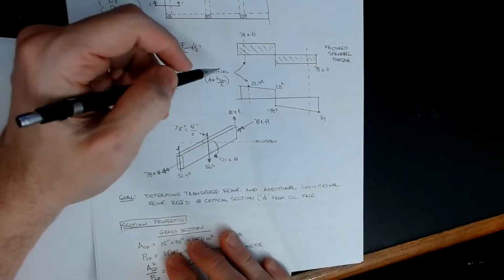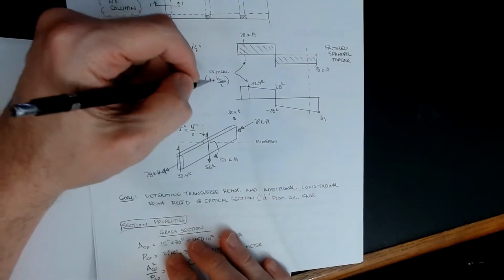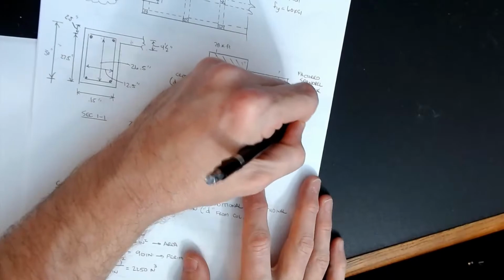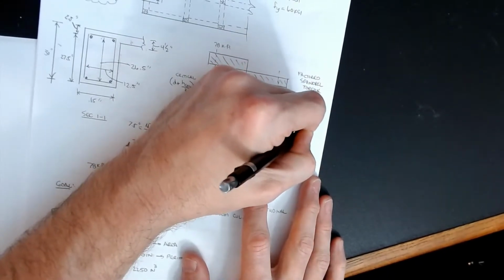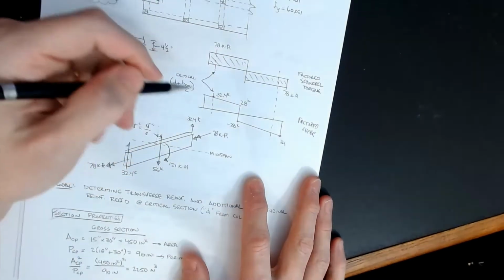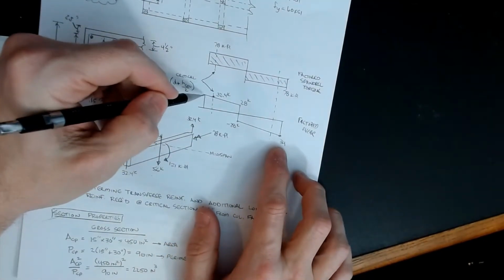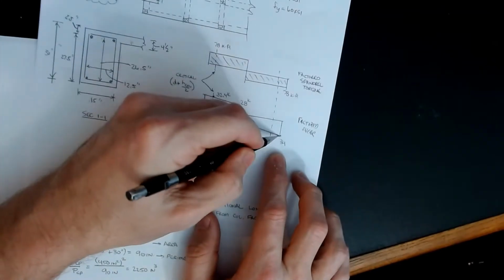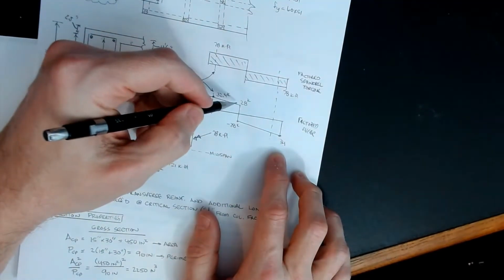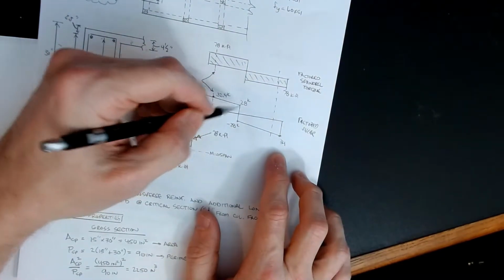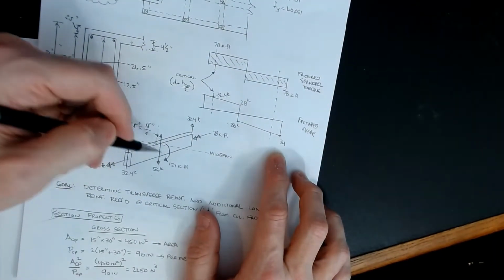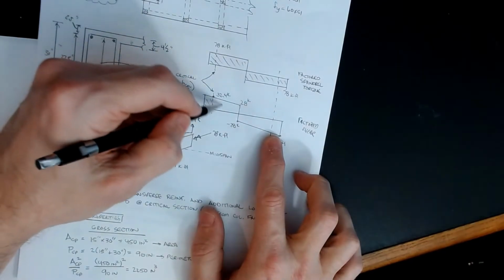And then we've got a crit. This is our factored shear here. I left that off. The shear reactions would be 34 kips of shear at the top, 34 kips at the bottom, and then it comes over and it decreases due to self-weight to 28, and then you get the 56 jump that you're seeing here. So this is the shear diagram that we have happening.